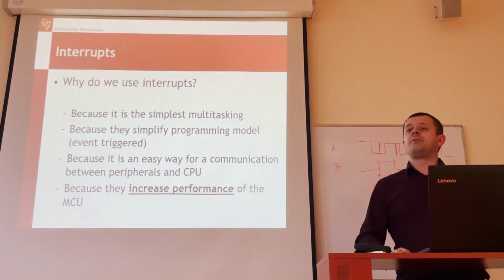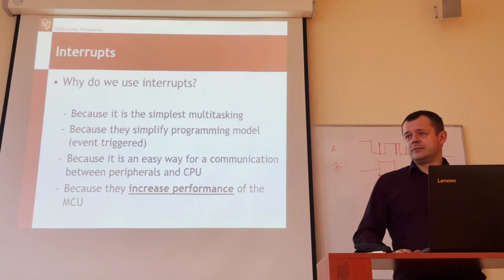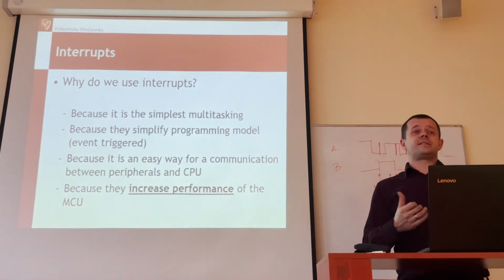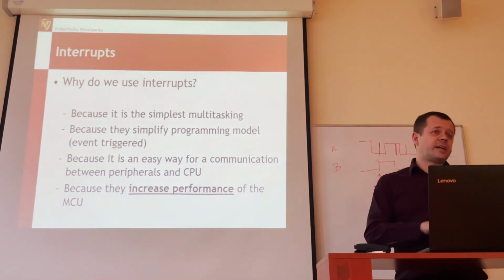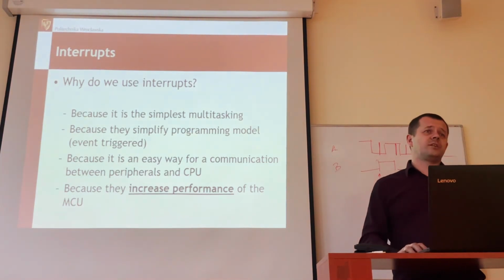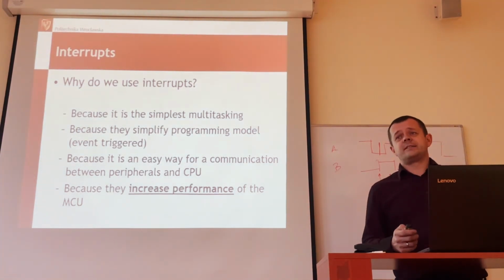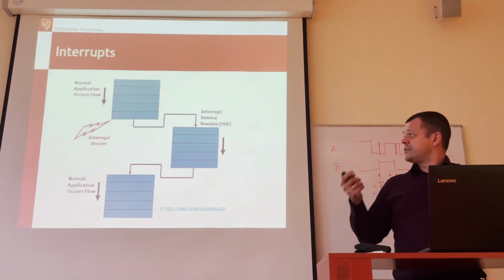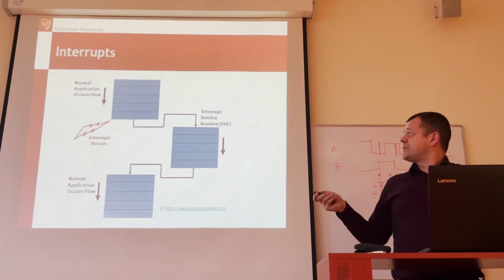We call it polling such a peripheral. So this polling is possible, but polling takes time, because the microcontroller has to have time for checking the status. With interrupts, it's naturally way simpler, because the microcontroller does its stuff, and then when the particular event happens, the event is serviced and executed.